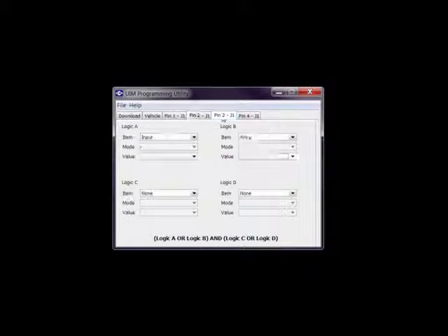Next we'll go to pin 3. This one, once again, we'll set up kind of a basic, very simple statement. Say we've got telematics running on the vehicle. We want to capture an ABS event. Well, the UIM can provide that information. So what we're going to do on pin 3 is select ABS, go down here and scroll down and find ABS event. And while it's already selected, we're going to just show that ABS event is true.